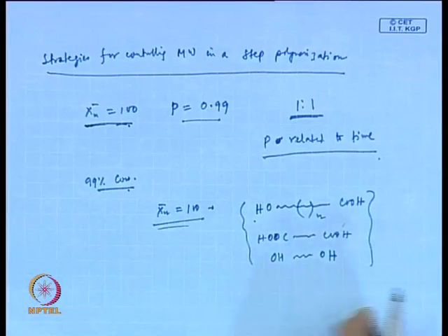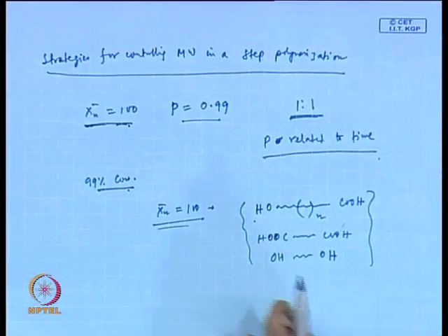These can react with each other or with a polymer backbone and degrade the polymer or build the molecular weight. So, at the end of your molding step, the molecular weight might be different from what you targeted, and your properties will be different.